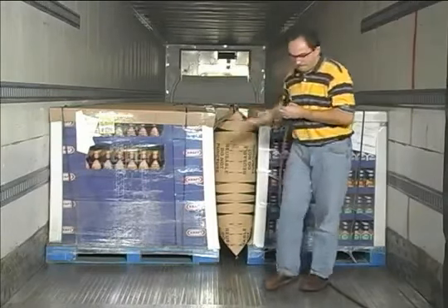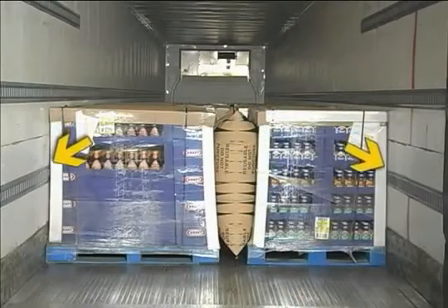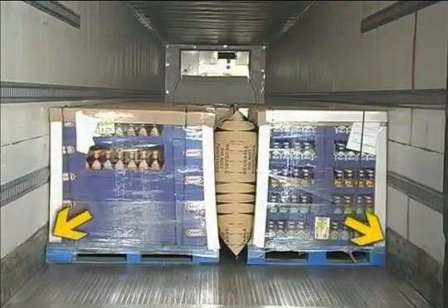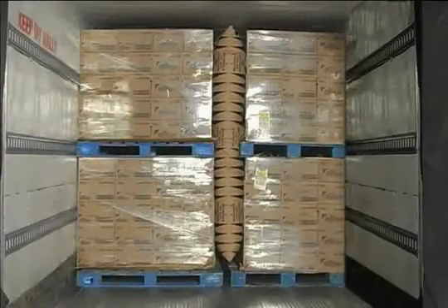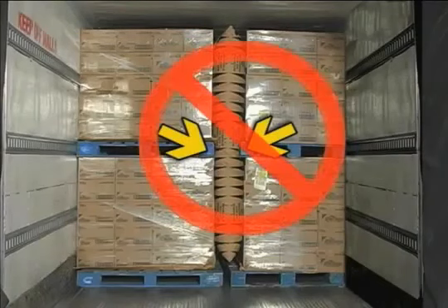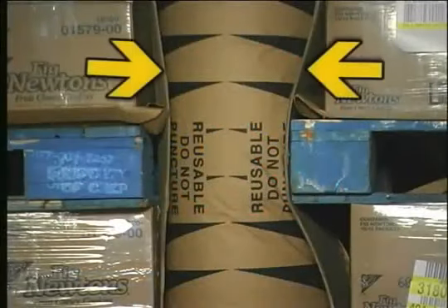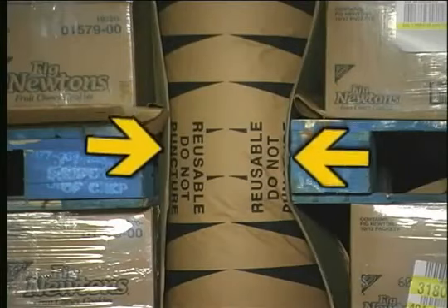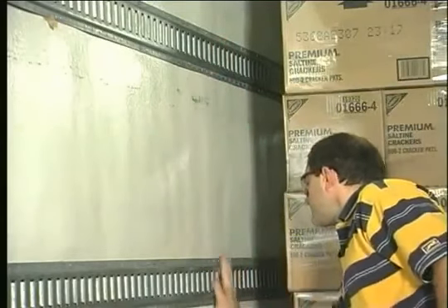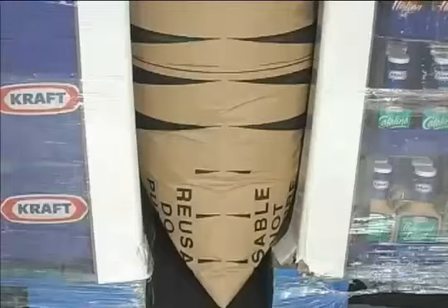Verify that the airbag is secure and the freight is positioned against the trailer walls to create a bulkhead for optimum freight securement. In order to prevent airbag punctures, never place the airbag in contact with the corners of the pallets, sharp objects, or pinch points. Use pieces of cardboard to protect the airbag from any potential damage. When using airbags against trailer walls, verify there are no splinters or metal protrusions.